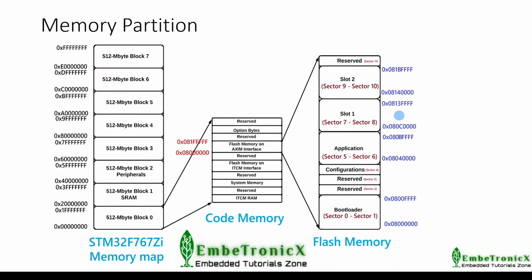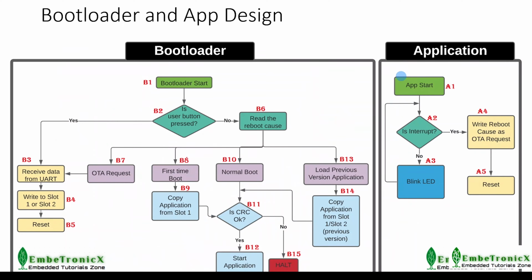We have everything ready, haven't we? Oops, we have forgotten to design the bootloader and application. Let's design that. First, we will see the bootloader operation and later we will see the application. When you press the reset button, the bootloader starts running from 0x08000000. One more thing I want to clarify.